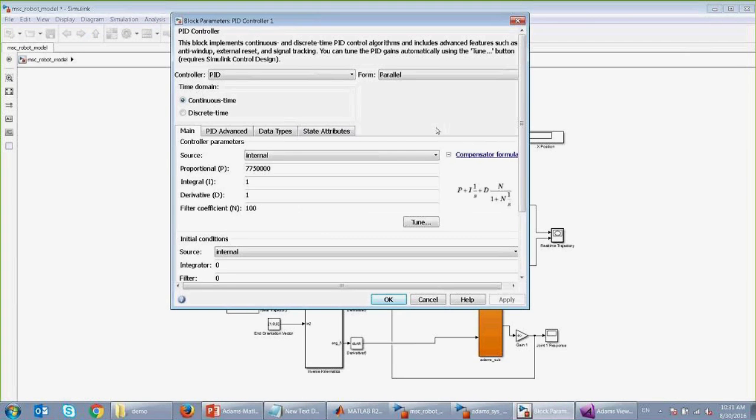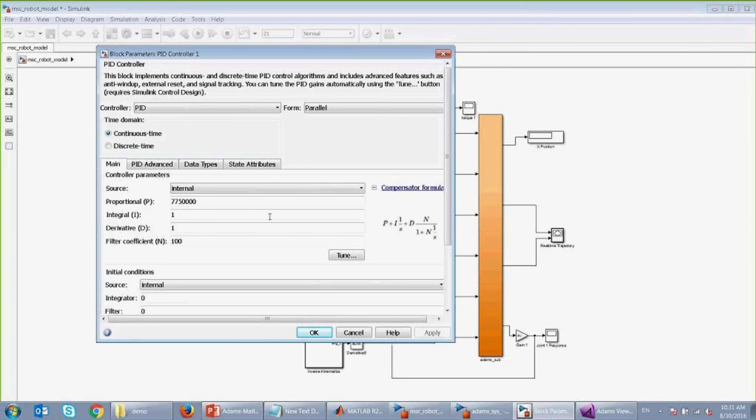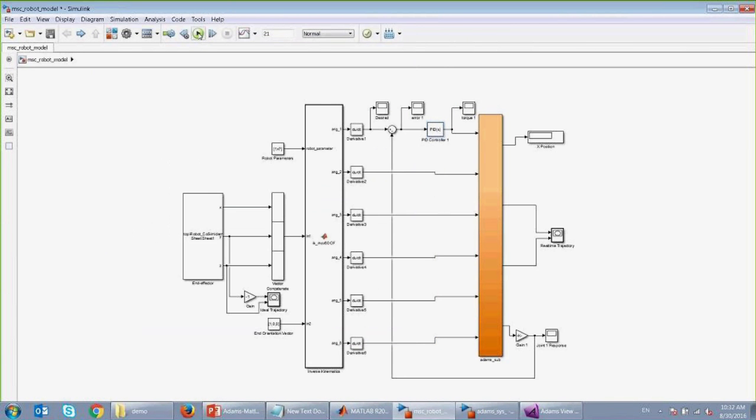There's also a lot of things you need to modify. For example, this PID controller, this proportional, this P is very critical actually. We have tuned this many times, so this is kind of the ideal number that we found for the specific PID control. So I'm going to try to perform a live run for this model, and then if it's successful, we'll try to change the PID, the proportional a little bit, and see what are the differences. Just to make things more interesting.